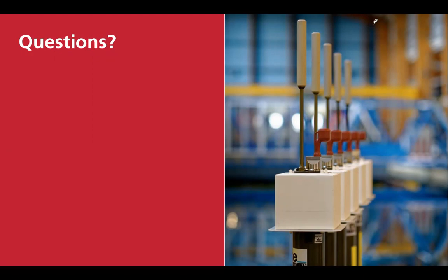Yeah, I had a question on the proximity effect. You guys saw that when you were within 10 centimeters of the air-sea interface, your conductivity measurements were bad. The group I work with does a lot under ice. So would we expect something similar within that 10 to 15 centimeter range of the ice-ocean interface? Our conductivity measurements might start to go bad.